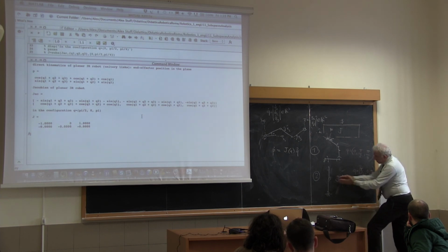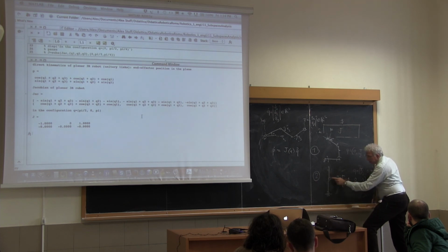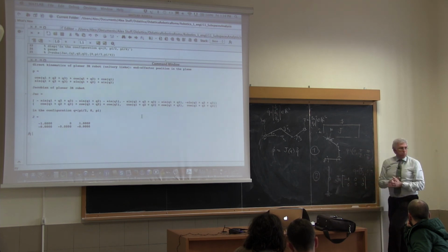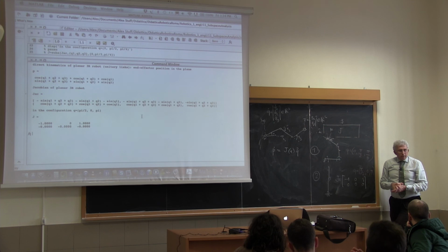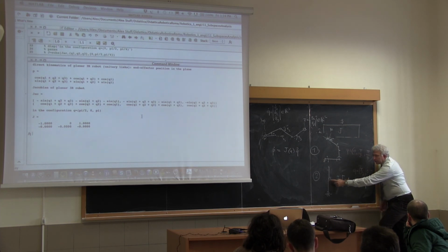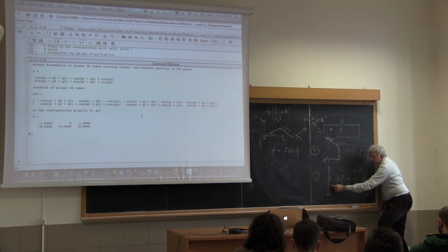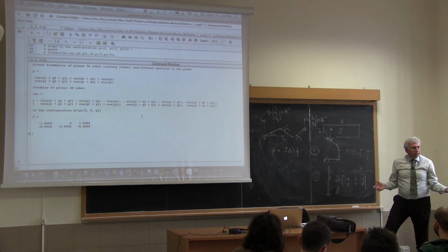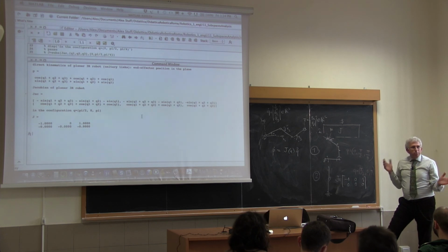Instead, I can generate velocity in this direction for the end effector in multiple ways. Not only that, if I'm moving joint 2, since there are 2 zeros here, this will not affect instantaneously, pay attention, neither this direction nor this. So I don't move the Cartesian end effector by moving joint 2.